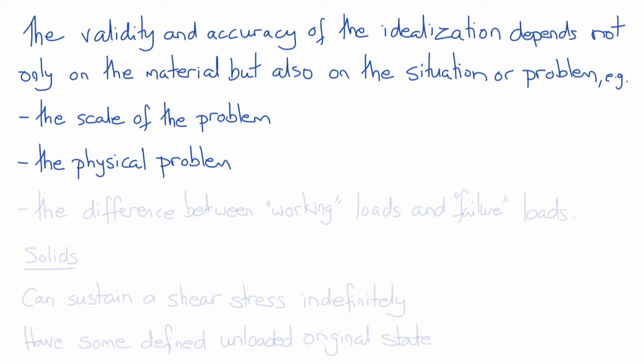But if we were interested in the way ultrasound waves propagate, which is also a problem that can be solved with the equations of continuum mechanics, then we couldn't use the assumption of incompressibility because, in fact, the very propagation of sound waves depends on the fact that fluids like blood and air are slightly compressible, and the difference between the ultrasound densities that we see in the lungs and the blood is dependent on the difference in the density between the air in the lungs and the blood in the vessels.